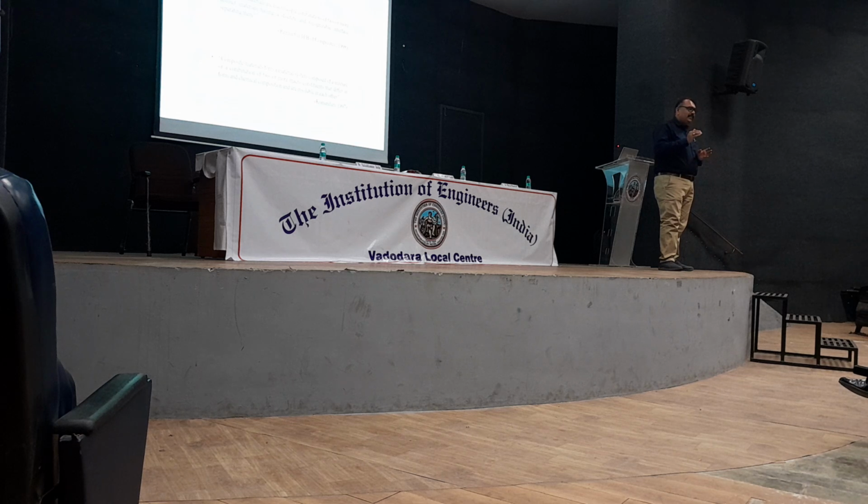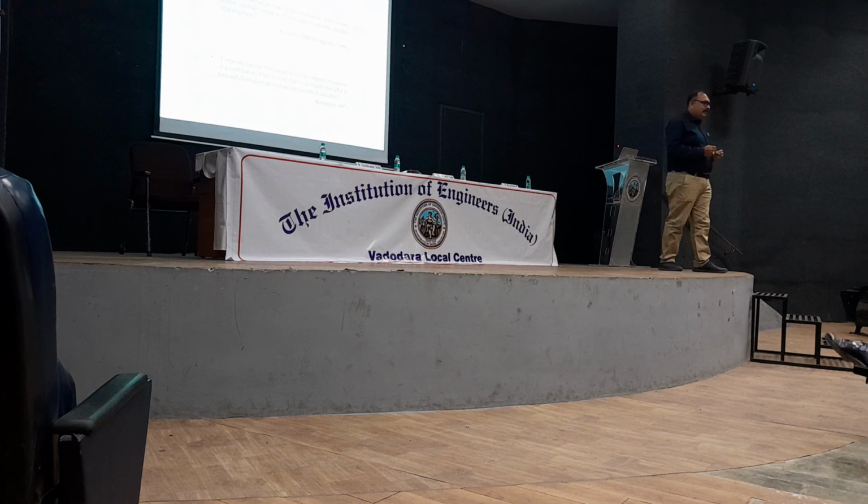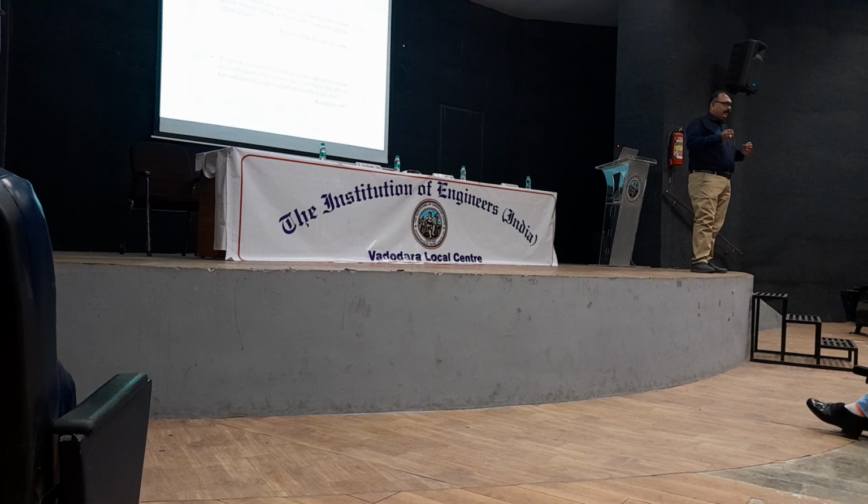Because for stress transfer, we require a medium. Because fiber is a load-bearing member. So we have developed the equations for the EI, interface elastic modulus, using various mathematical techniques. But that is through experiment, not only mathematics. The property of the fiber is known to us, or we can test it. The property of the matrix we can develop or we can test it.